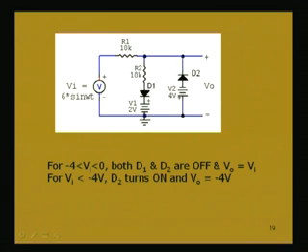So, the diode will be conducting, and when this diode D2 turns on, what will be this voltage? The voltage across these 2 points, as this diode is ideal, has no drop. When the diode is turned on, an ideal diode does not have a drop, so it will simply be this type of circuit at these 2 points.